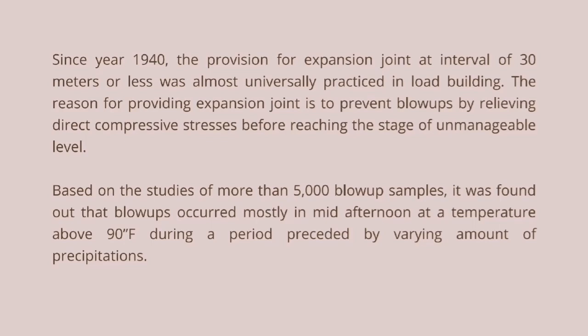Since the year 1940, the provision for expansion joint at intervals of 30 meters or less was almost universally practiced in road building. The reason for providing expansion joint is to prevent blow-ups by relieving direct compressive stresses before reaching the stage of unmanageable level.